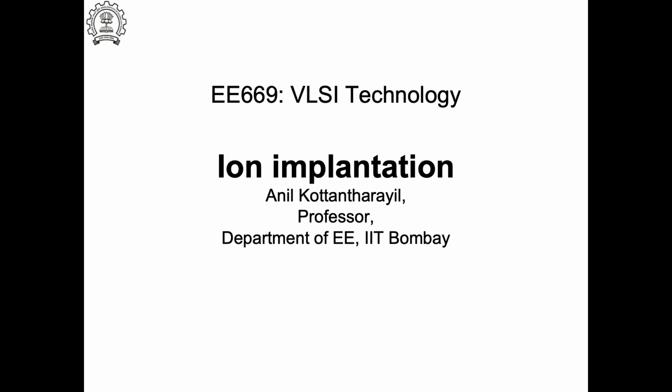So the annealing process should be targeted to completely eliminate the defects. That is very important. But in VLSI, you also would like to reduce the extent of diffusion during the annealing process, because we don't want deep junctions in your VLSI. Source drain junctions, extensions for example, have to be like 1/3 of the gate length. If they diffuse too much, then I would not be able to have controlled shallow junctions in the device. So this is very important.